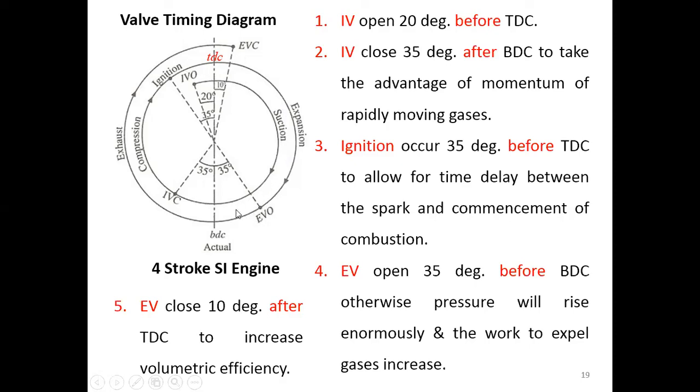And from the valve timing diagram, you see that the inlet valve opens here, 35 degrees before the top dead center, right? Because we know that there is a high pressure from here. Start from here, you have high pressure, and the piston moves down, trying to reduce this pressure to convert this pressure into work, right? But even with this piston moving down, it may not be rapid enough or fast enough to reduce this enormous pressure, right? So the exhaust valve opens early, right?